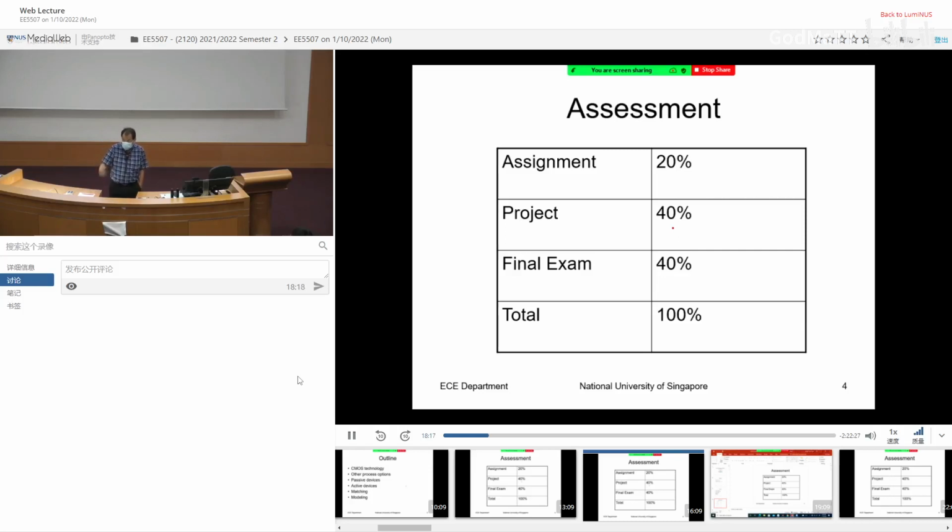We need to predict, as I mentioned. You need to be able to predict it before even the chip coming back. How did people do that? They built all these process variation into the model. And then you can actually launch the Monte Carlo simulation, and they will try to see how will the offset voltage vary. So the EDA workshop simulation will show you how to do all these things.